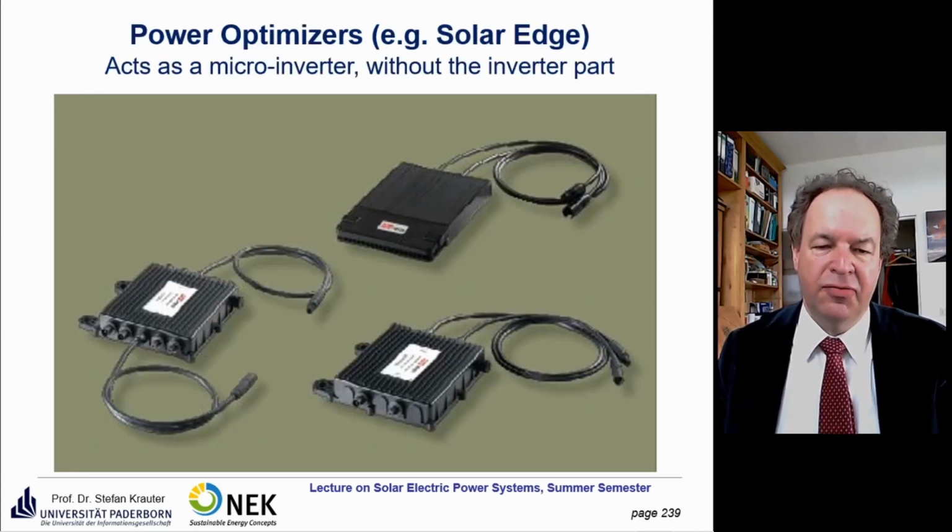These are some examples of those power optimizers. It's not really a microinverter. You have just a maximum power point tracking device at each module or at each subarray, as we saw before.